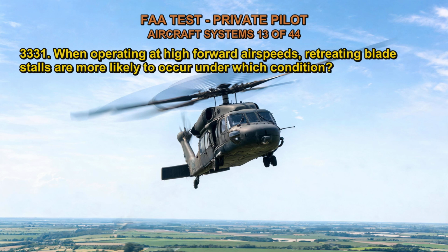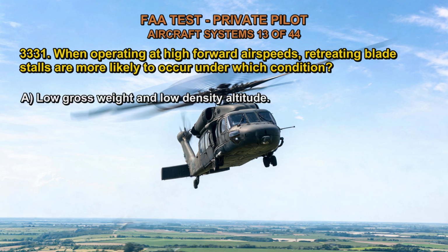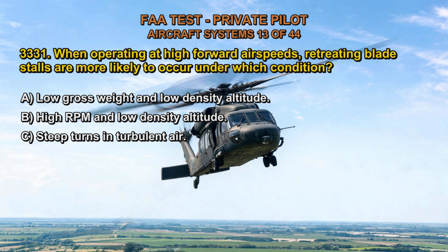3331. When operating at high forward airspeeds, retreating blade stalls are more likely to occur under which condition? A. Low gross weight and low density altitude. B. High RPM and low density altitude. C. Steep turns in turbulent air. The correct answer is C.